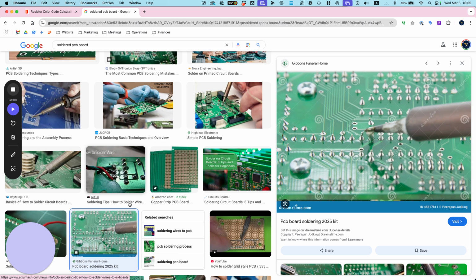Okay, 3S battery. Let's take a look at that. 3 cells. Our nominal voltage is calculated at 3.7 volts per cell. Times 3 cells, what would that be? 11.1. 11.1 volts. Okay, so that's this position right here, just like what we see here.